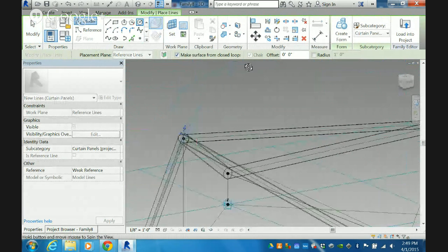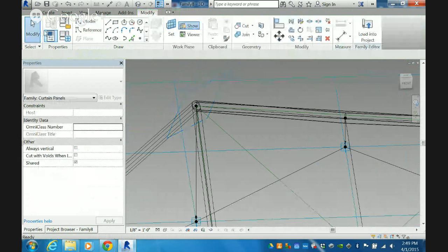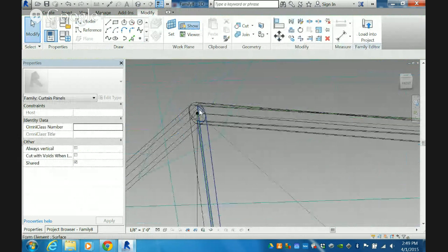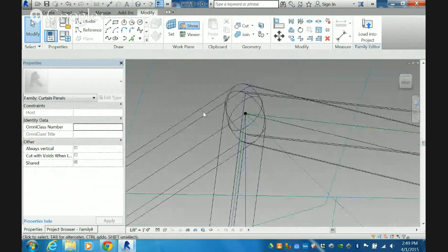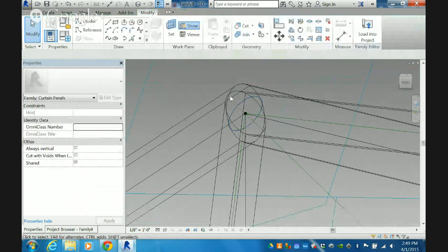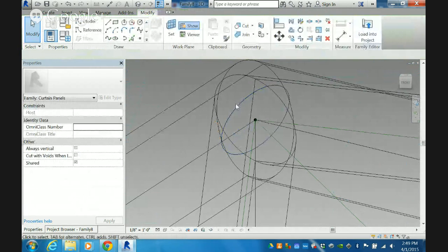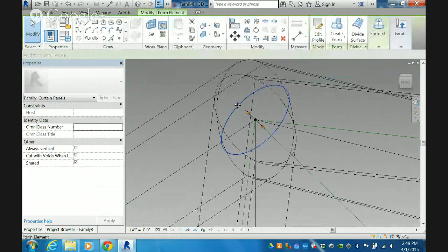Let's get that on the right plane. Yes. And same thing with this guy. We'll just do 3 inches. Small fella. We'll just have to probably zoom in here because we've got a lot of geometries pulling together now, and tab around until I can get the entirety of the circle. Be careful whenever you're selecting on the circle. It might want to click the hemisphere. We don't want that. We want the whole thing. You'll just have to tab around until you get to the whole circle.